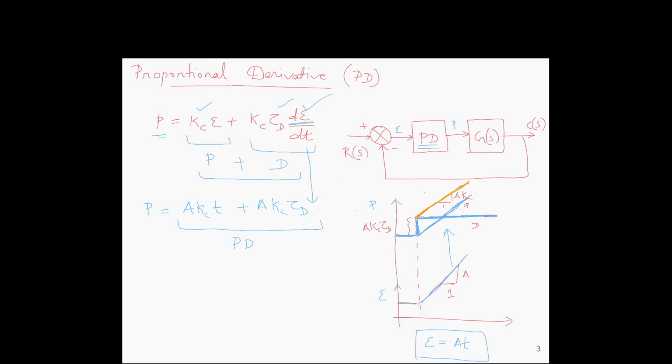So that prediction is used by the controller to take control action. It is anticipating some change in the error. The slope gives information that in future the error is going to increase or decrease. Based on that, the current control action is taken. That is why it is called anticipatory control. And the transfer function of the controller is Kc into 1 plus tau d s.